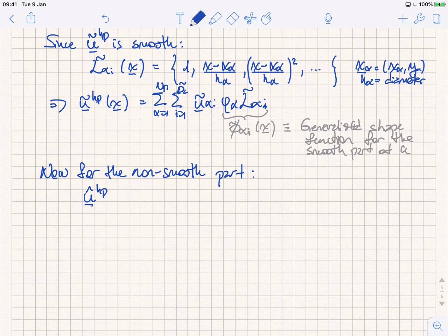So we are thinking in terms of the combination of HFEM and PFEM, whereby you can improve the accuracy by reducing the size of the mesh elements and, at the same time, increasing the polynomial interpolation. That's why I call it HP. The size of the elements takes care of the H part of this approximation, and using generalized high order enrichment functions takes care of the P part of this interpolation.